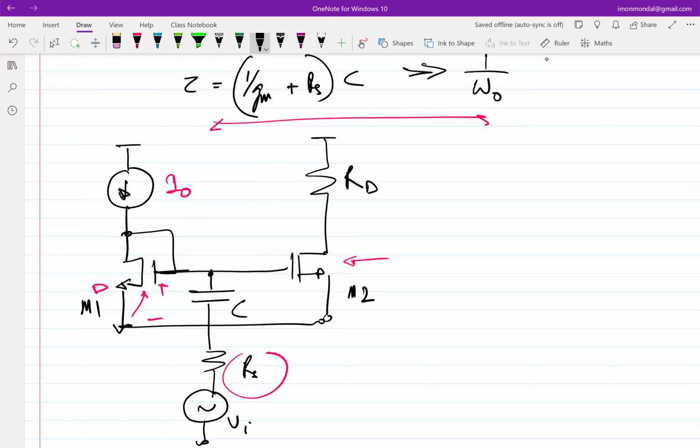But in an IC, in an integrated circuit, the capacitance is a function of the area and the thickness between the plates. Now, thickness between the plates is technology dependent. You cannot change it, right? When you are making an integrated circuit, you have multiple layers of metal and they are only separated by a fixed amount of thickness. You cannot change it. You can only change the area. That is the designer's control.